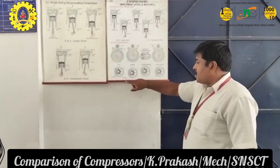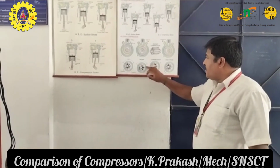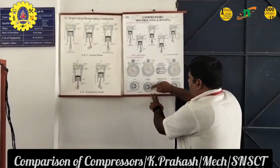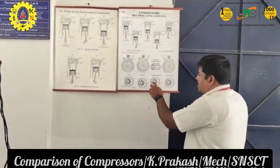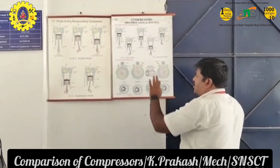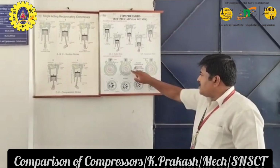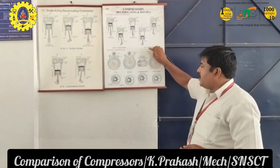See here in a rotary compressor what happens. This is the intake. When the piston is moving here, the inlet suction port is open. This white colored area is the free area where the air is coming inside. During the compression, as this is rotating, the suction port and the discharge port are closed, so the air is getting compressed. Then the discharge port is open, and when the discharge port is open, the air is going outside.